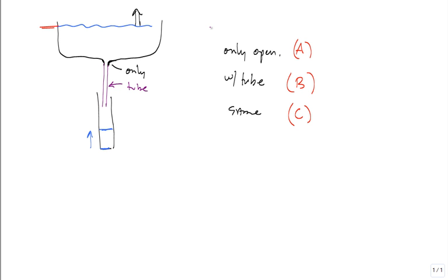Apply Bernoulli's equation from one point to another point. True? And so I would do it for here. I would pick a point, maybe this is point 1, and I'd go to point 2. Or I go from 1 to 3. Right? In case 2, what is the pressure at 2 if there's no tube? What is the pressure at 2 if there's no tube? Equal. Atmospheric pressure. It's equal to P1.